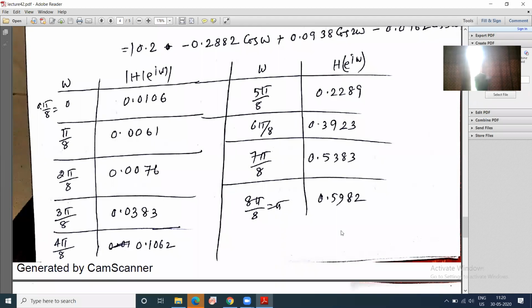Now, while plotting the data in examination, first we have to see what we have calculated. Does this look like a high pass filter type or not? Because after plotting, if you understand this is wrong, then you have to come back to here. But while calculating each value, after 2-3 values, while designing a high pass filter, in your mind, for omega c to pi, this value will be 1, or there should be a pass band.